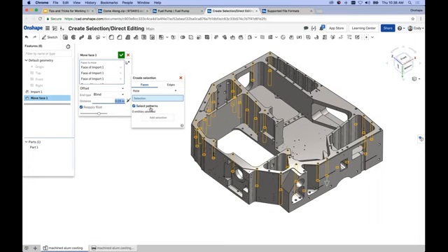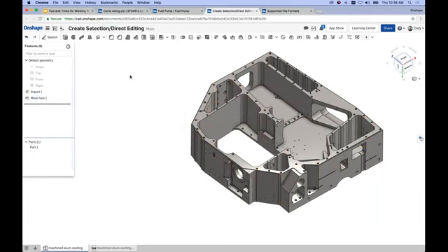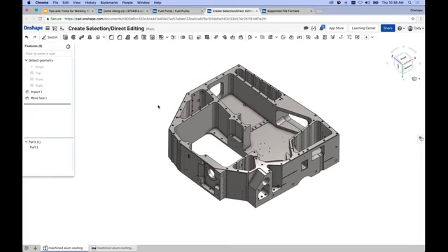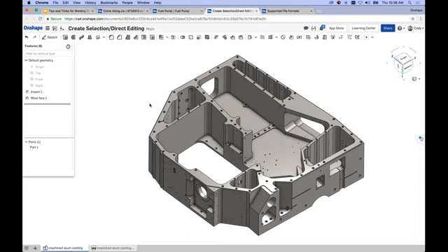That's where select patterns is useful. Right? So I hit the green check OK, and now I've offset 20-something holes by 30 thousandths of an inch, right? And relatively quickly. So that is again, really using the create selection tool and the offset move face option.